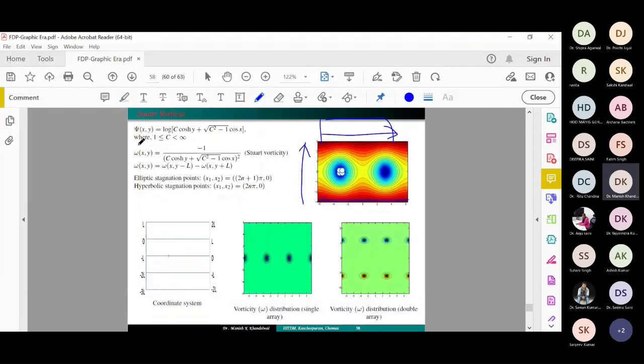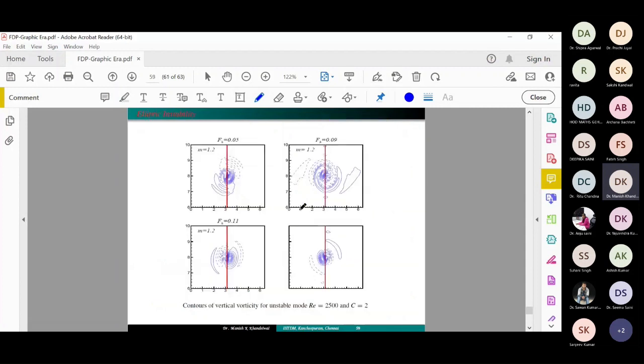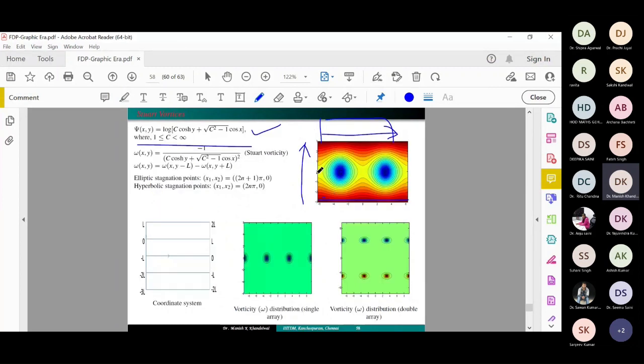Sorry, this is a basic flow, and it is completely two-dimensional, not one-dimensional. I put the main governing equation, the Navier-Stokes equations, then develop the linear stability equation, apply linear stability theory, and develop a few results. These results give very nice information. You see three different types of points here. This looks like an elliptic structure, and this is the hyperbolic structure in mathematics. That point is called the elliptic point, and that point is called the hyperbolic point.